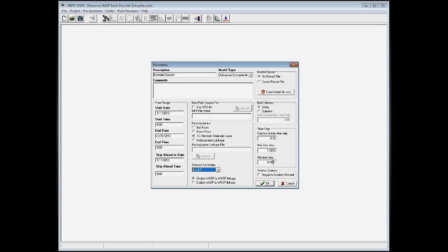This screen over here for the time step options is, you don't really get the option to set the time step in WASP. WASP automatically calculates the time step as a function of transport, loadings, and kinetics. The top one, fraction of the maximum time step, basically what that says is if WASP calculates a time step of 1 day, the model will actually take a 0.9 day time step. So this is a way for us to just throttle back the time step optimization.